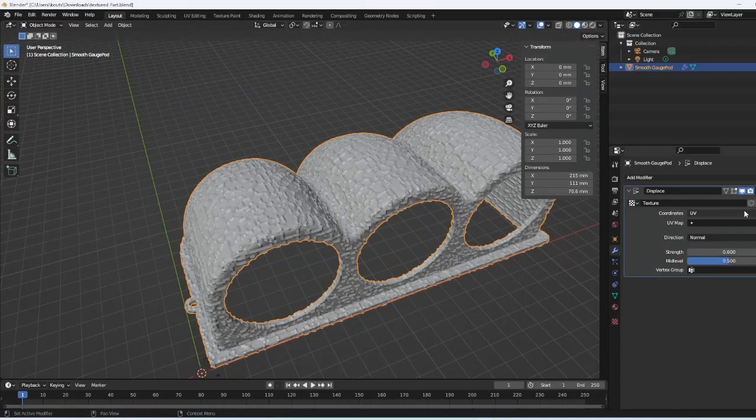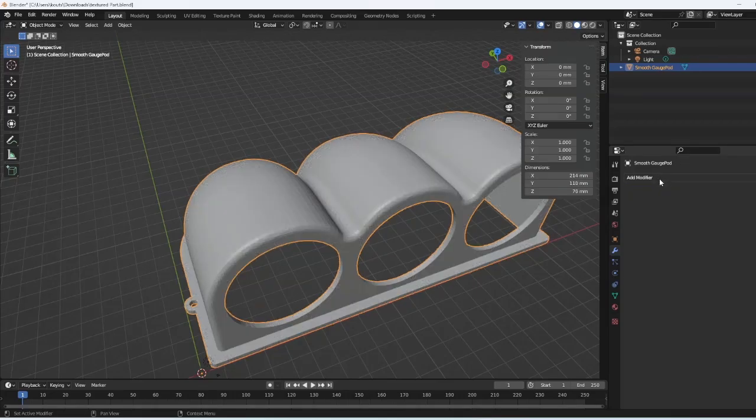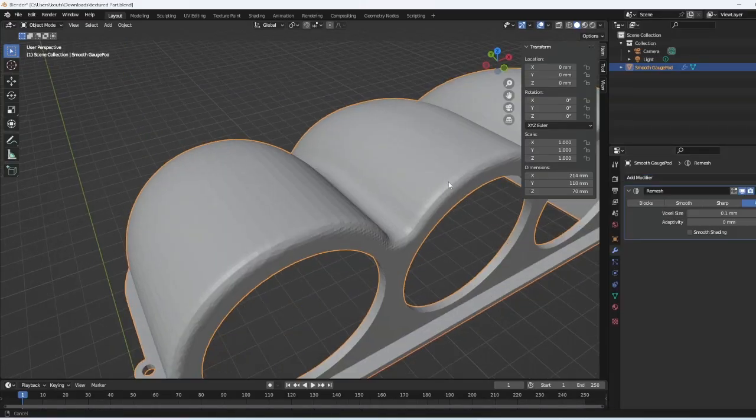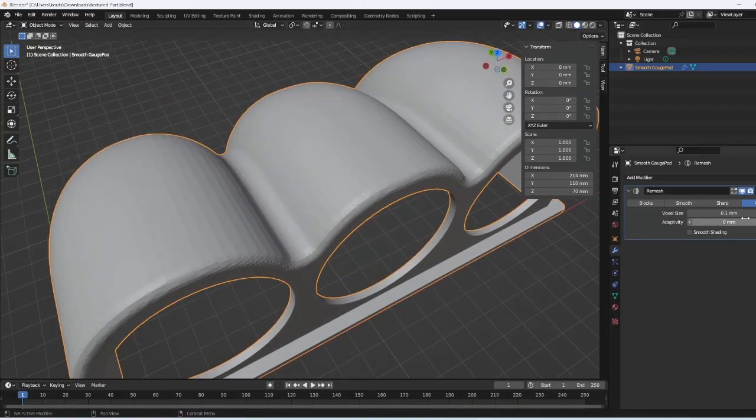So yeah, we need to basically go back and cancel this and make sure that we can remesh this, so we've got a much more dense mesh. So I'm going to hit remesh again. And instead of 0.5 on my voxel size, I might go to, I don't know, 0.2, something like that. Okay, this is not a big enough change. Let's just write that in there, 0.2. And I'm going to apply this by going to the drop down, hitting apply.